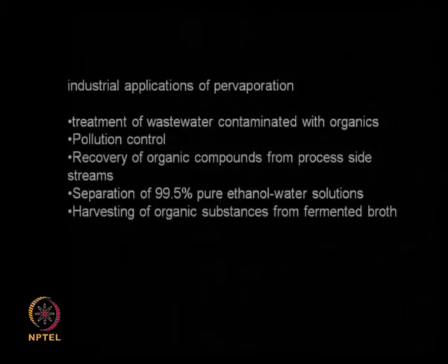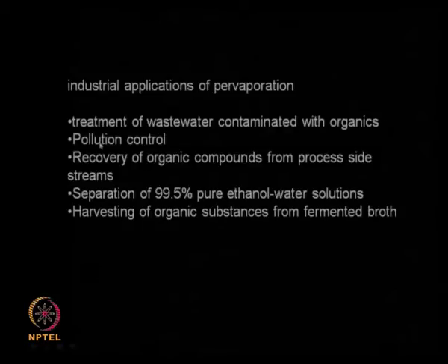So industrial applications of pervaporation are now becoming larger and larger. It's been realized that it's got a lot of advantages. So there are large scale installations of pervaporation. So we can use it for treatment of wastewater contaminated with organics. I am just interested in removing some amount of organic present, not a large amount, only a very small amount of organic contamination is there and I want to remove it.